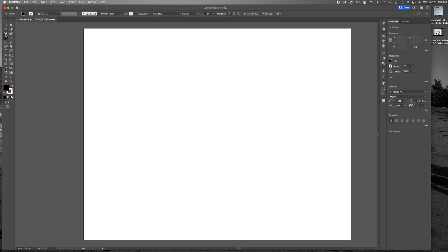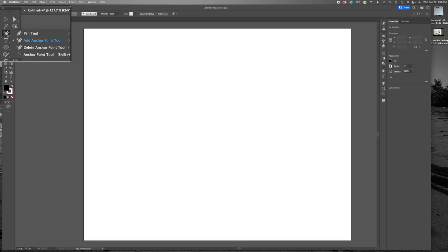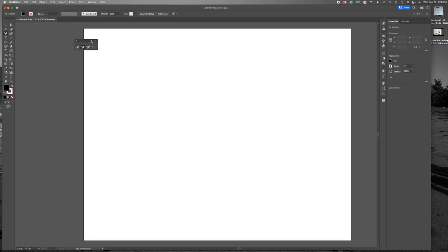Another thing you'll notice, for example, with the pen tool that we will be using, is that when you use the flyout menu, on the right side, you'll notice an additional arrow. If you click on that arrow, it actually allows you to pull those tools out of the toolbar. This is handy when you're drawing. You need to quickly switch back and forth between various tools of a similar nature. You can actually position it anywhere on your artboard and use it in that spot.